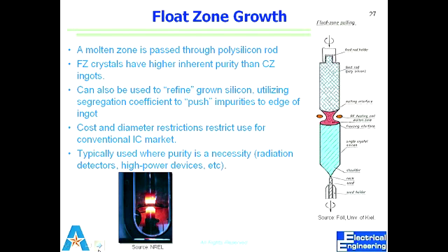Once we start moving, the float zone is simply a zone where we have molten the silicon. Once we move it to the top, the lower part follows the orientation of the seed. Right? So what results is crystalline silicon. Again, you can slice it and get the wafers out.